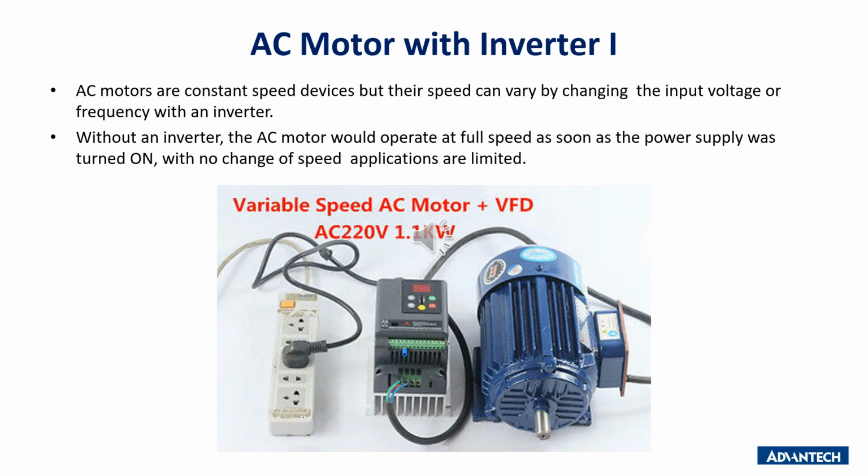Combination of AC motor with inverter. Homes, office buildings, and factories are supplied with AC electricity at various frequencies and voltages such as 50 Hz and 60 Hz. But AC motors are constant speed devices. So, how can we modify the motor's speed according to our applications? In the electrical field, we can take advantage of the inverter. It will change the input voltage or frequency which directly modifies the motor's rotation.